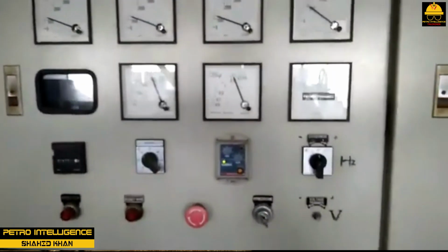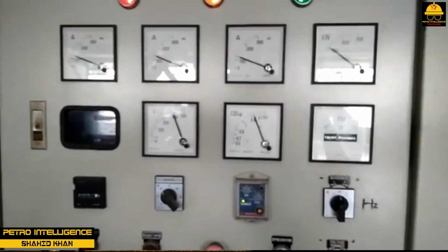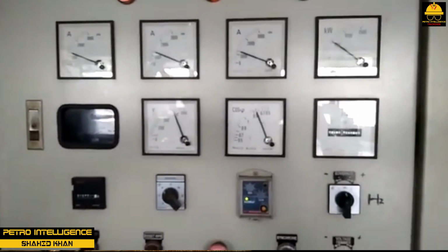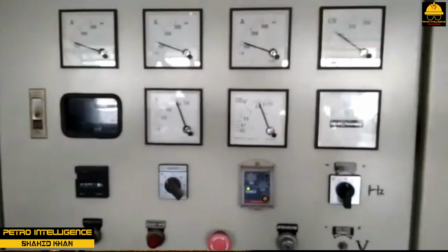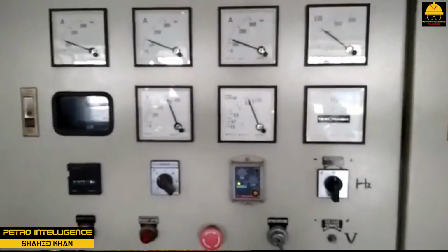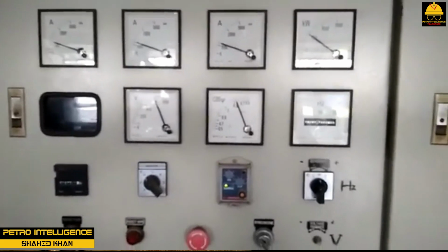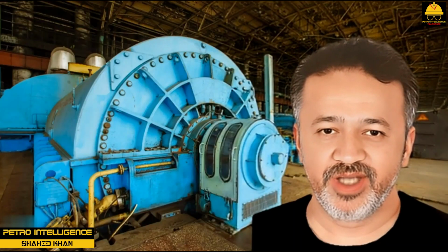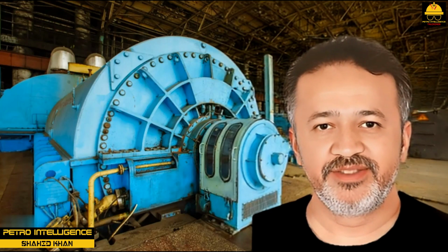As discussed earlier, the governor system is responsible for the speed at which the turbine operates. Occasionally, the mechanical linkage between the governor and governor valve will bind. This binding causes the steam turbine to hunt. Sticking or binding problems can be resolved by lubricating the linkage on the steam turbine.